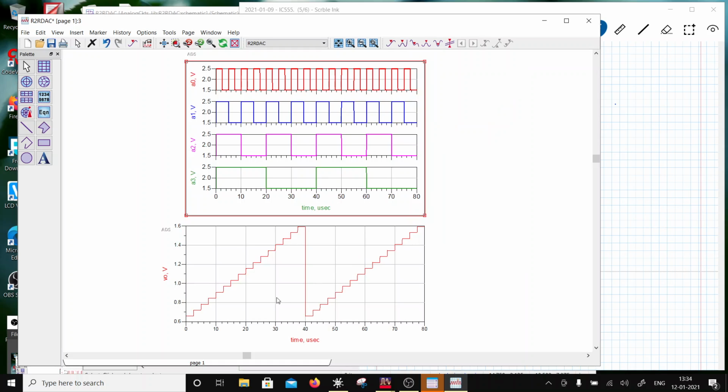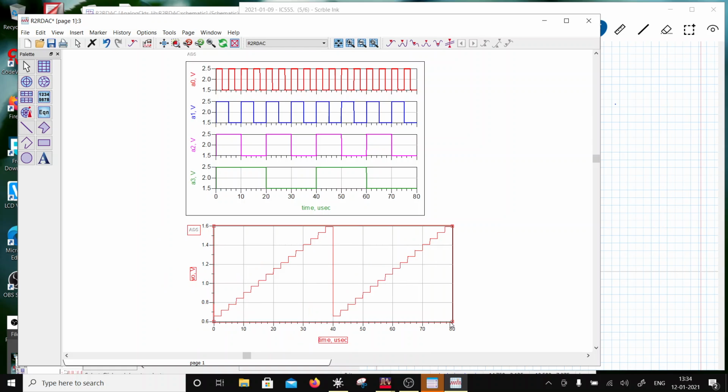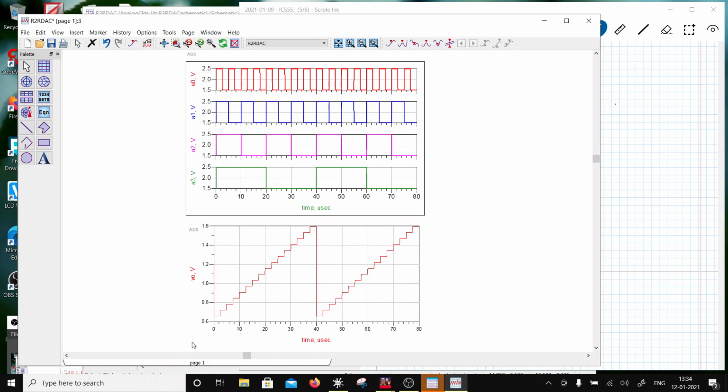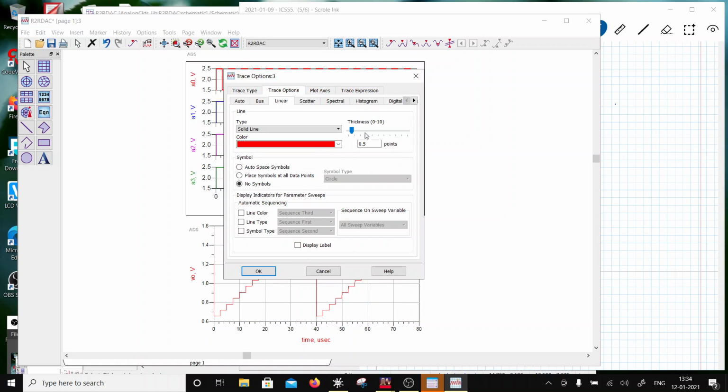And that's what it is supposed to do, right? It is going to be a DAC, right? And the concern is the linearity of the steps, but it is monotonic. That's the only achievement here. But what I'm trying to say here is, this is the simplest implementation of a DAC, an R2R DAC, right?